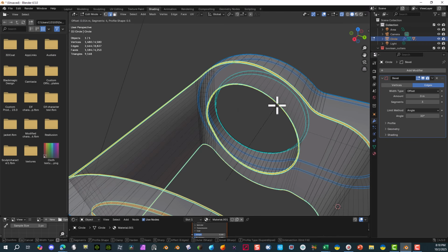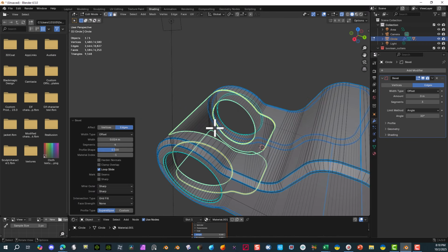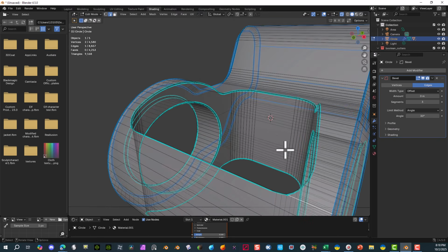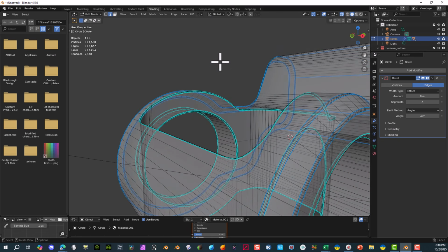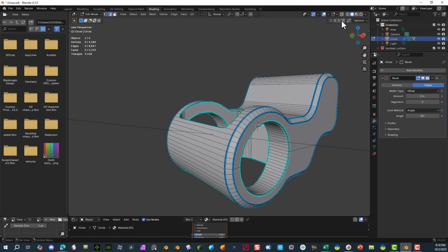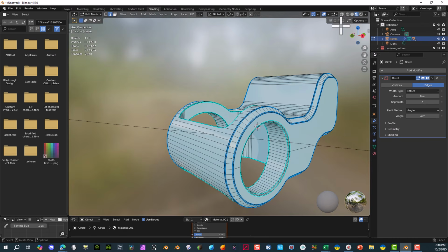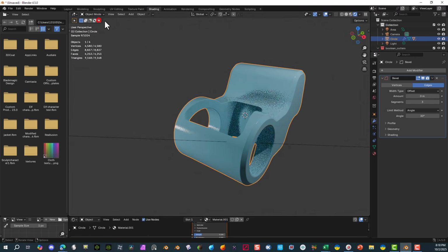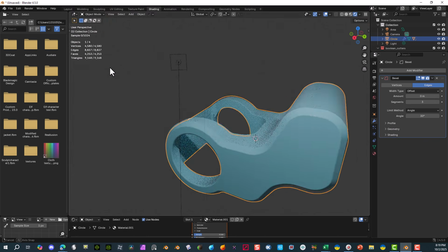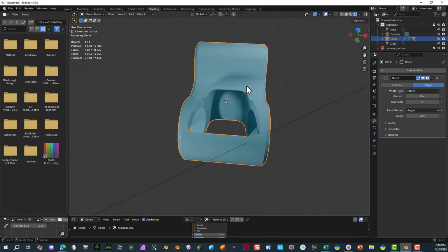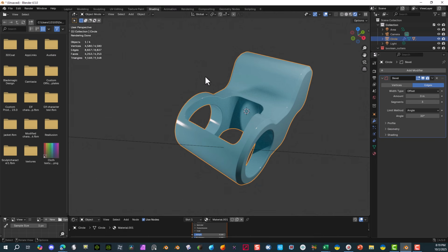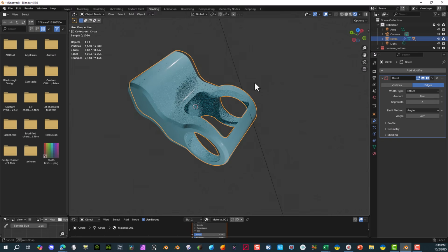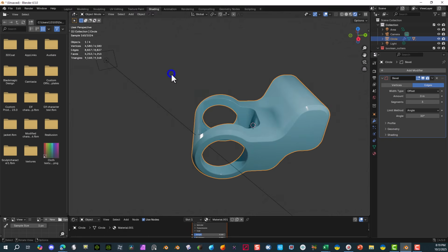So we're going to hit Control B and pull this out. Be very careful when pulling this out. If you do too much, it's going to cause a problem. Just do a bit less than what I did. I had some edges that were kind of messed up on the intersections on the corners because of the edges. So just keep that in mind. Go very small on your pullout. Even though it looks fine from the video itself, it is a little bit chaotic on the very corner pieces. So again, lighten it down a little bit more than what I did.